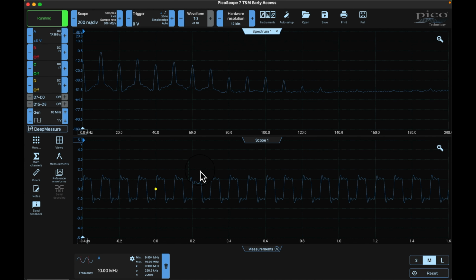You see the two windows on the bottom. See this tab right here in the middle? It says scope. So on the bottom, I have my scope waveform. And look at this. It's time-based, 0.4 microseconds, 0.2. So I've got 0.2 microseconds per division. Up here at the top left, it says 200 nanoseconds, which is 0.2 microseconds, right? The other thing I want to point out up here, see samples says 1 kilosamples. Just pay attention to that, I'll point that out a little bit later, okay?